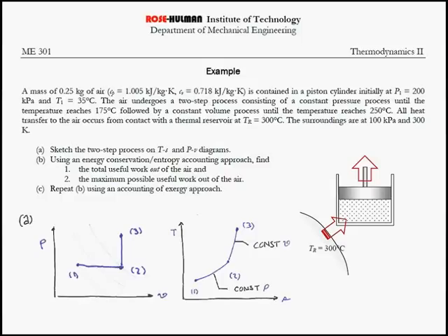These lines on the diagram, right here in the PV diagram, are lines of constant temperature, and each one of these up and to the right of the previous one is a larger temperature than the one before that. You can figure out the shape of that curve from PV equals RT. Not the exact shape, but certainly the trends involved.